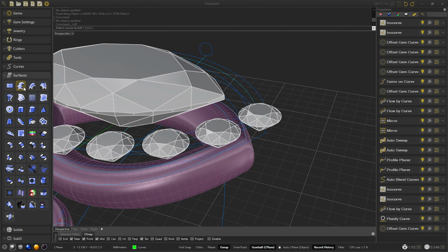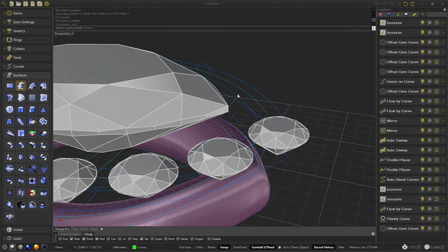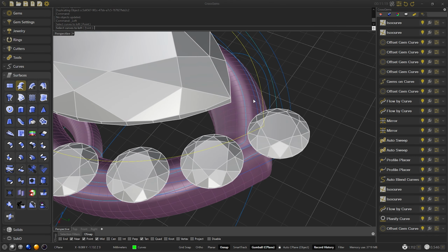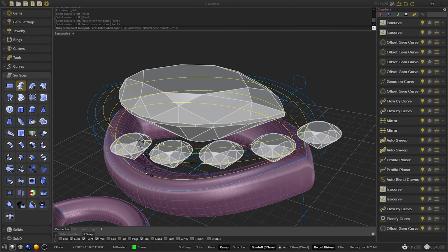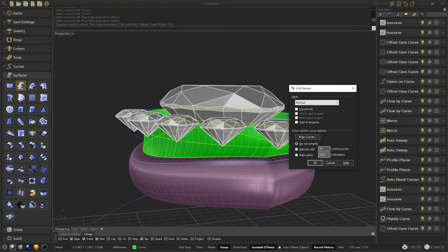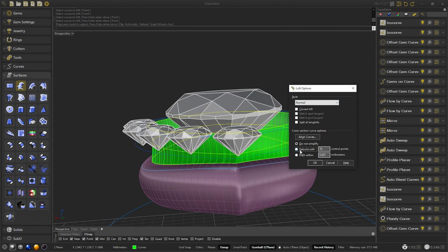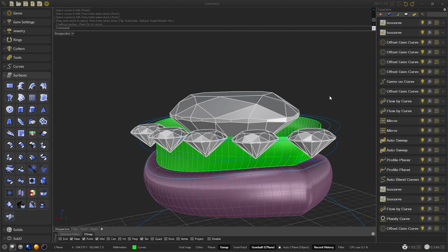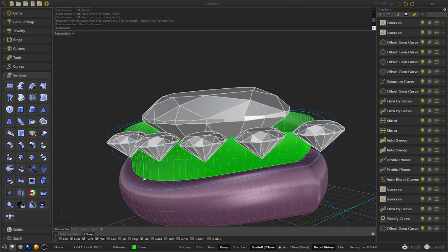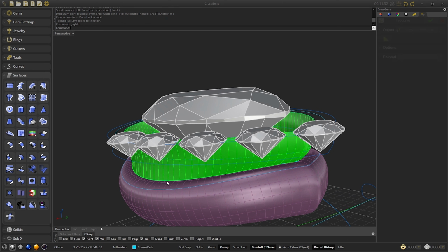So go to Surface, select Loft, and use the inner offsets and the isocurve. Confirm. Now select Reveal and choose Uniform. We can see that the isocurve needs to be more inside to create a curved shape. So we are going to edit it a little bit.